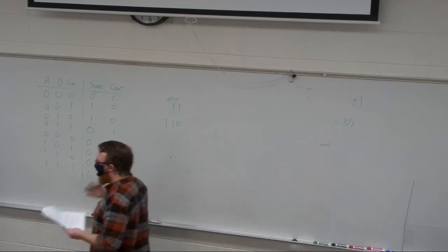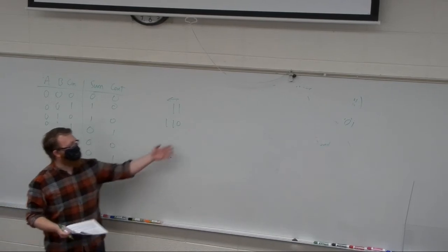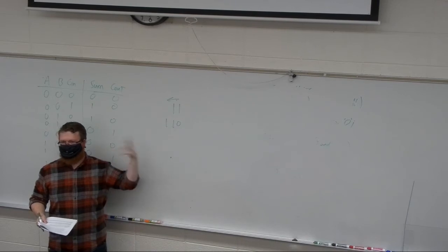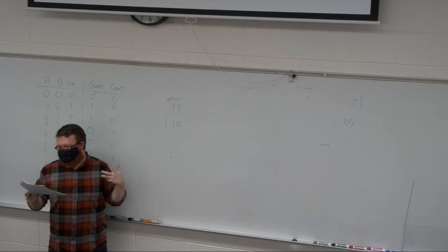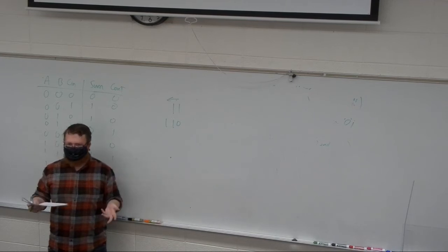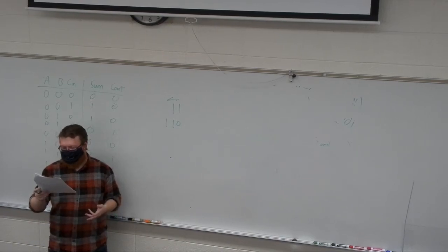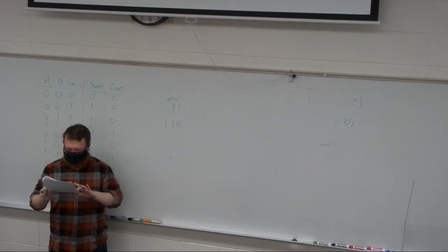There are multiple ideas of shifters. So in this one, we would call it a zero fill shifter, because as I shifted, it filled with zeros. Other types of shifters is something called a sign extend shifter, which is helpful in signed operations to make sure that they stay the same if I shift them in different directions. Let's see what other ones they want you to know about.